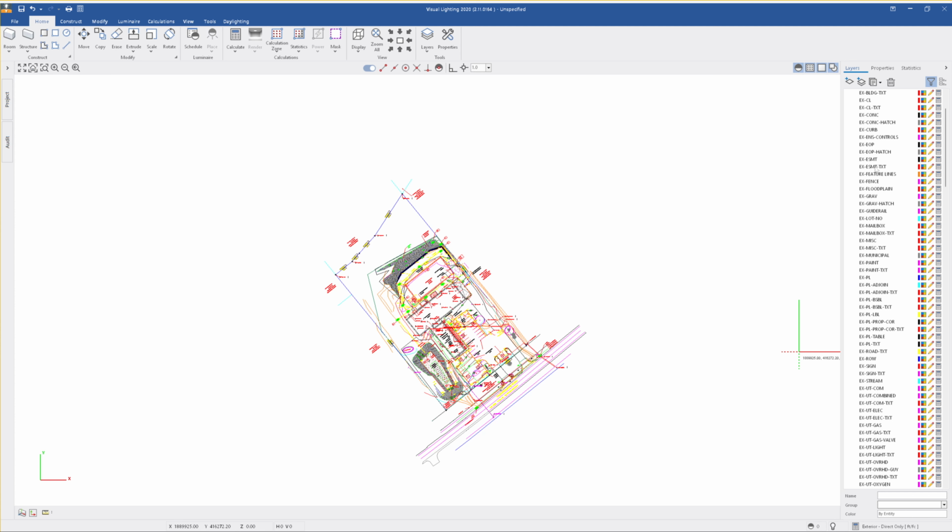Feature lines are another really important one that can make things confusing, so I get rid of those. So that's usually the existing layers. You can get rid of all of your profile layers because we're not worried about those. And really the main ones I try to get rid of are the contours, just because that's usually the thing that clutters up the CAD file the most visually. And again, I'm just right clicking after they're selected and saying delete layer and entities.